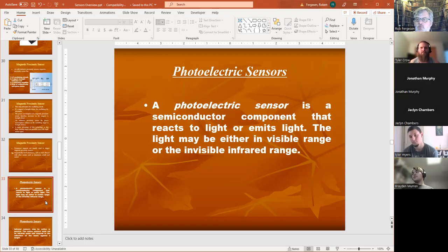In the category of sensor, which are also becoming more common, which aren't really proximity sensors, are photoelectric sensors. Photoelectric sensors basically use light energy to see if something's there or not. And they are getting cheaper and cheaper as well. And they are becoming more and more flexible with a lot more features. It used to be that the only photo sensor out there was one like your garage door sensor that would send a beam across a room. And if you crossed through that beam, it would cause your garage door to go back up or trigger an alarm or something along those natures.